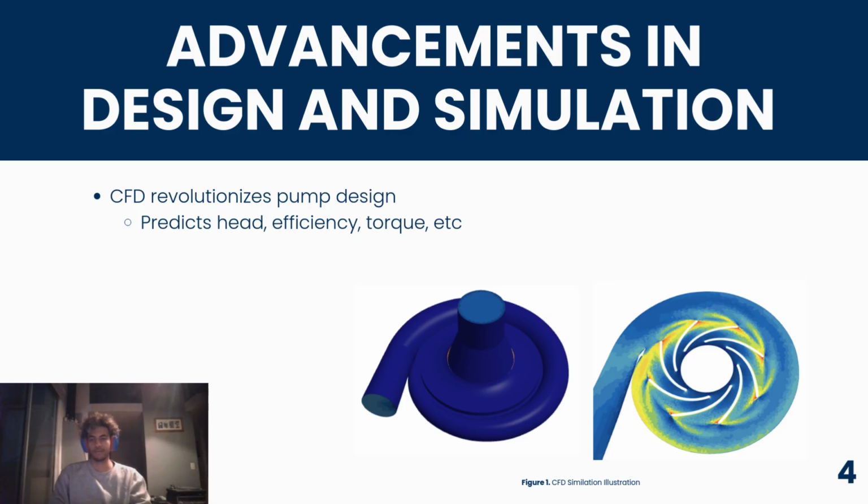Recent advances in computational fluid dynamics, or CFD, have completely transformed pump design. With CFD, we can analyze complex internal flow dynamics, assess hydraulic losses, and even predict cavitation phenomena. These capabilities enable us to accurately forecast performance parameters like head, efficiency, and torque under different operating conditions.